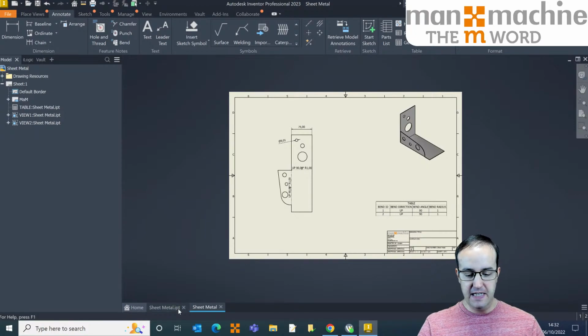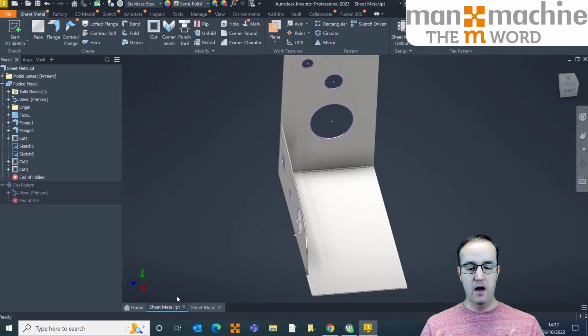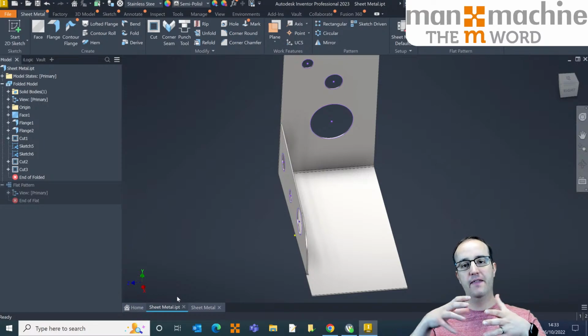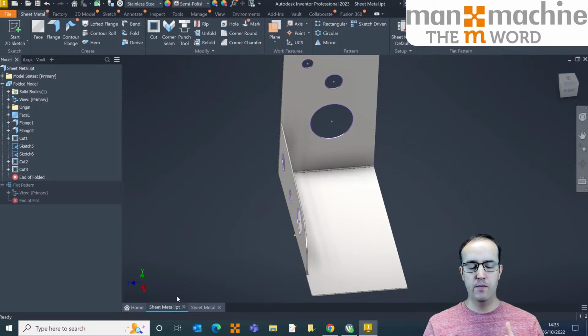Other things that you can do with that sheet metal, we can use sheet metal with multibody solids for the past 3 years or so now in Inventor, if not a little bit longer. So if any of you are used to modeling in context and then turning that context into an assembly, because you've said new solid, that functionality is also supported within the sheet metal workflows.